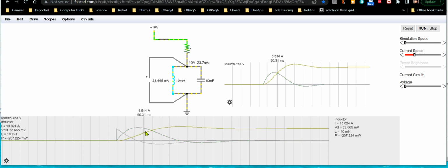because at that point the inductor is starting to chime in, and that's why the current flips on the capacitor and goes to a discharge state. So here, the current in the capacitor's gone negative now, and it starts at zero because it's starting to feed its energy off into that inductor now. You can see its current peaks down around here just before the inductor is fully charged, but the voltage across the tank circuit is starting to drop, and eventually that hits zero, right? It hits zero right about here, about when this current peaks.